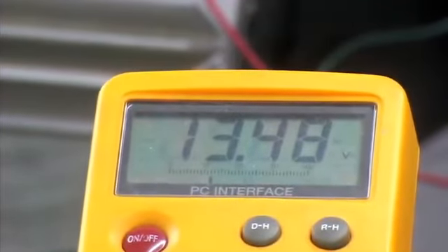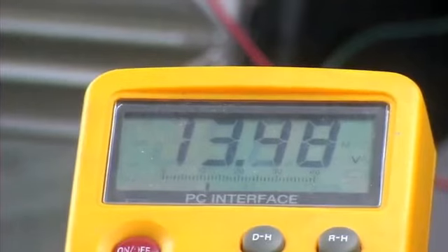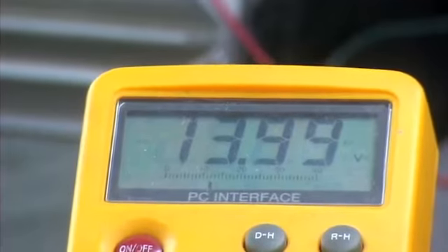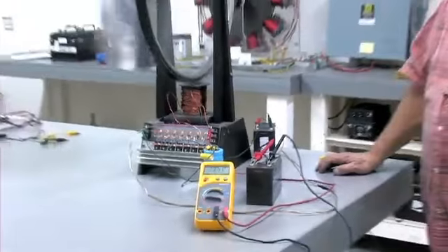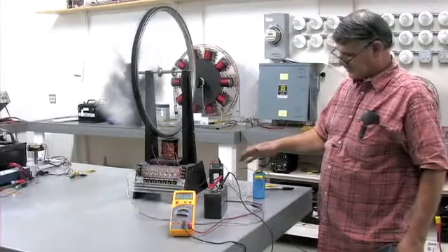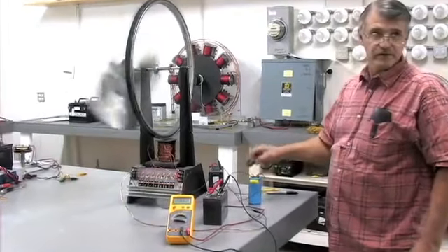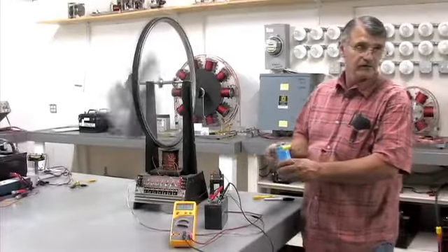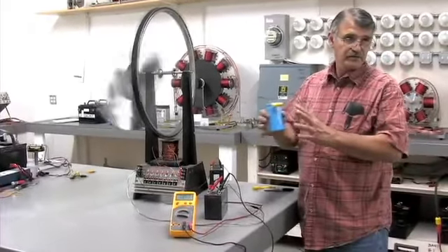You only had that on the capacitor for what, a few seconds? Yeah, about less than... we want to discharge this capacitor. And then the other thing is, don't leave the capacitors open, because they sometimes build another charge. Do you notice that they build their charge when they're near to these machines? Oh, no. Just after we use them, sometimes they build up another charge, and we think that's the residual left over in the plates as they expand back.